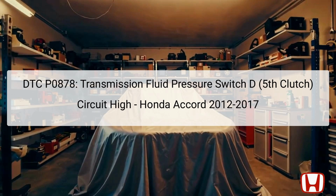If the hydraulic pressure is applied, the switch is turned on. Conversely, if no pressure is supplied, the switch turns off. The signal from this switch is sent to the Powertrain Control Module, PCM, which uses the information to ensure smooth gear transitions. A failure in this system can lead to poor shifting performance and may trigger the MIL, or malfunction indicator light, indicating that further diagnostics are necessary.